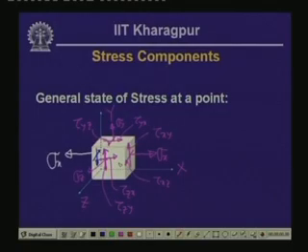Likewise, on the y plane, we will have the stress acting perpendicular to it, which is sigma y. The y plane in the x direction will have the shearing stress, but in the opposite direction of x, this being the other end. On this y plane in the z direction, we will have the stress tau yz.